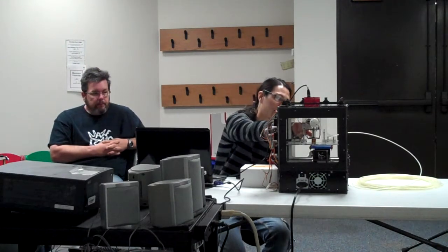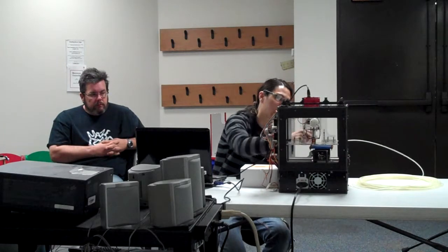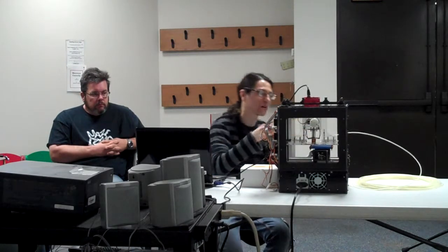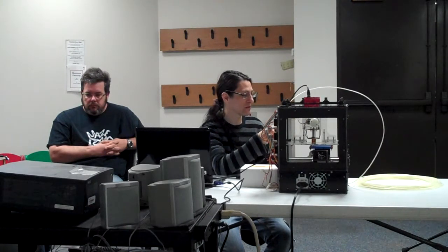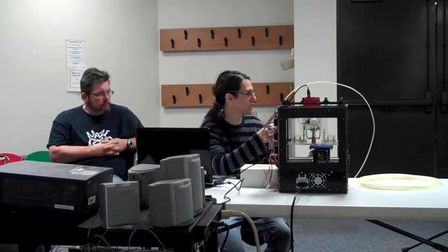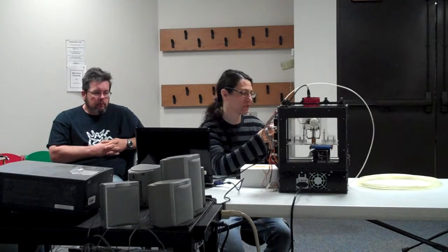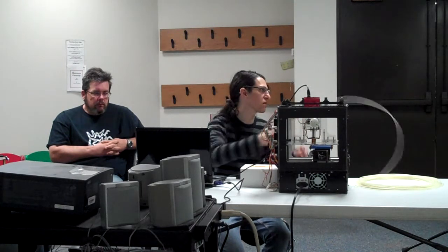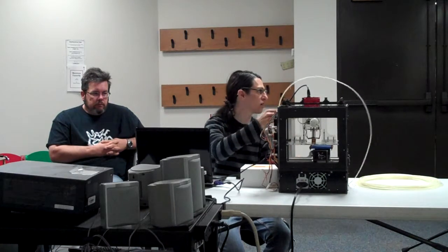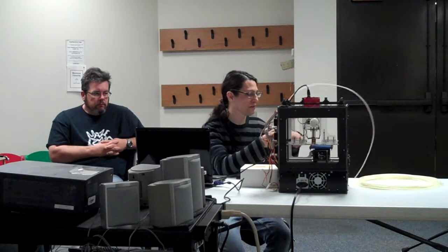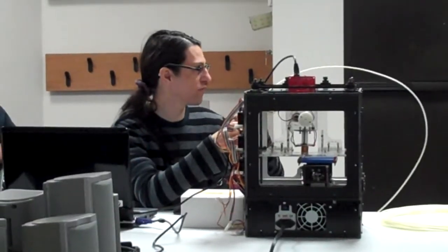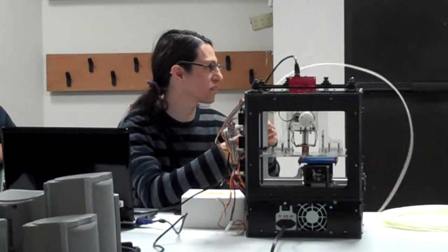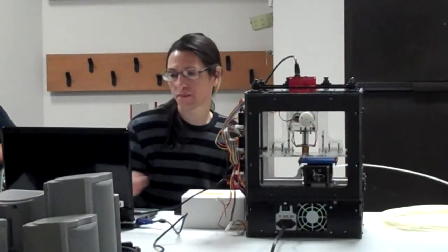It's on a DC motor, and inside it's got a tooth cog, but it also uses pressure to hold the plastic in. When it gets hot, sometimes the ribbed area will start digging into your plastic, so it doesn't have that bite anymore. It just chews it up and sits there. Then you have to take it all out and clean everything, because when that tooth thing gets filled with plastic and becomes a flat surface, it just slides on the plastic, even if you put in a new piece.